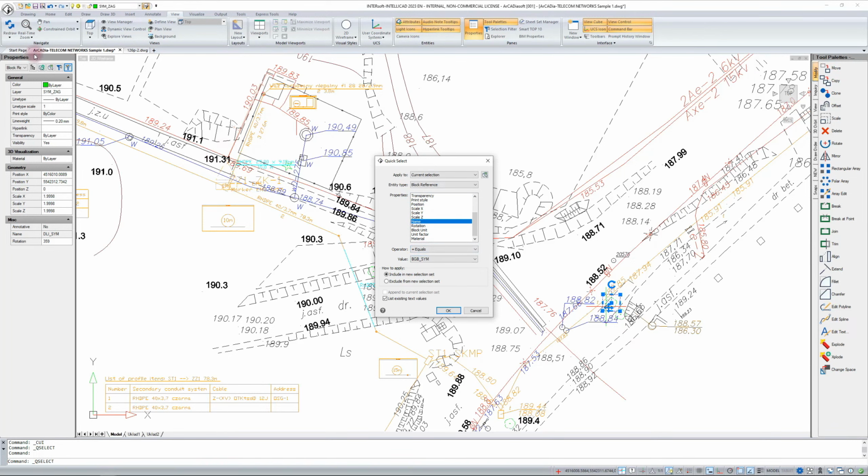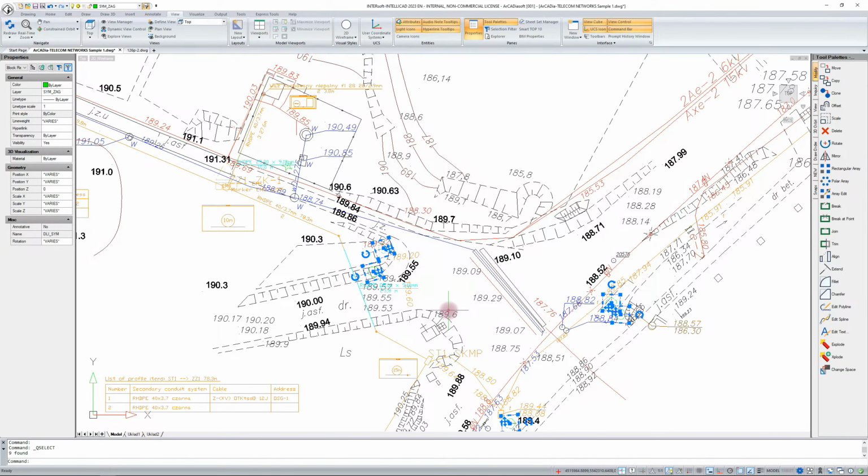I specifically opened the Properties window on the left side to find the name of my block here at the bottom. And I have to select it because when selected, by default in the Quick Selection window, the first from the list is shown. We find the name. Oh, I still have to change the usage for the items located, and it will probably deselect my selection. I'll want to apply this to the whole drawing, but I can apply it to a particular layer or part, so I can define it as needed. Once again, I find the name and I click OK.